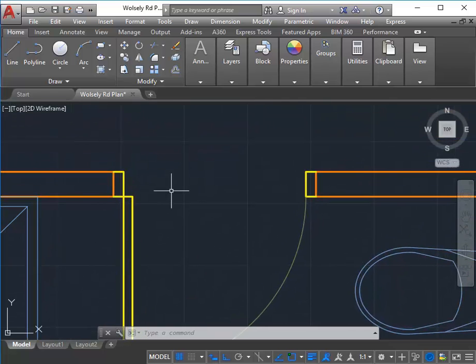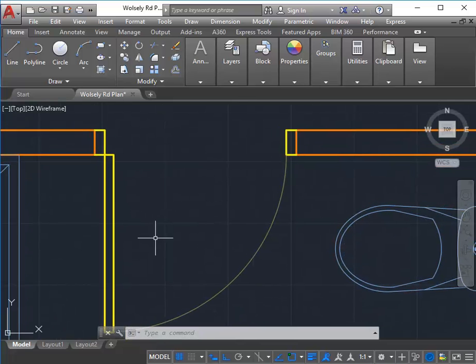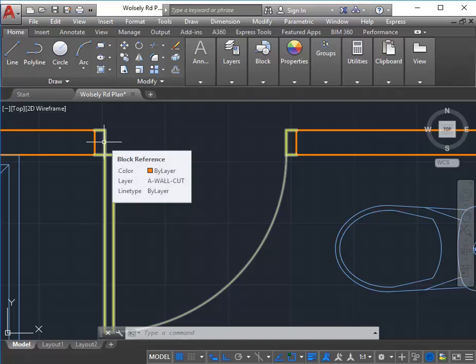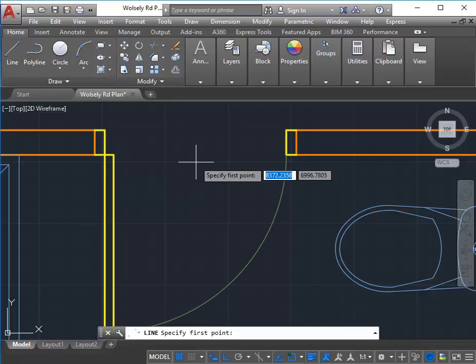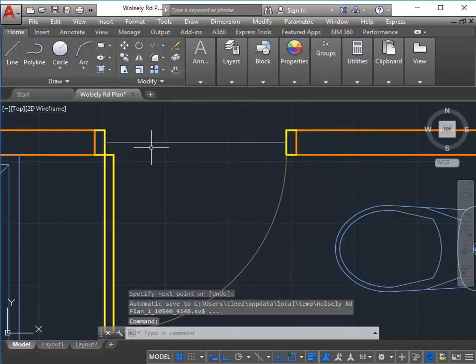So do you know where the tiles go in a door? Where do they finish? Often it does, not always though. In fact, not normally. Where the door is closed? Yeah, that's the key. So for good design, especially good interior design and decoration details, that's usually the best detail, to have the tiles edge concealed under the door when it's closed. And so that means that the tiles end up almost in the middle of the door opening. So if you draw a line from the midpoint of your door jamb across to the midpoint on the other side, that's a good point for your tiles to finish.